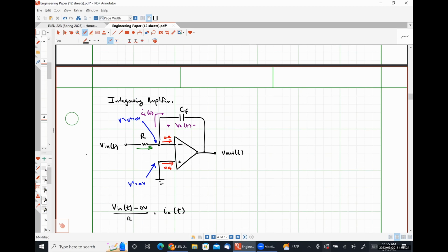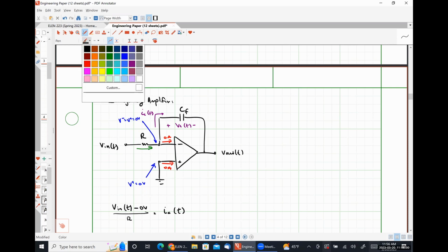Actually, so now we need to think about some things here very quickly. Because we're expecting to have some relationship between Vn and V out for this thing. And right now we have Vn in terms of IC. So how is V out related to VC? Let's start there. Exactly right. They're same magnitude, opposite polarity. Because V out, the positive polarity terminal is here, the negative polarity terminal is at ground. VC, the positive polarity terminal is at ground. So V out and VC are just equal but opposite. So let's write that over here.